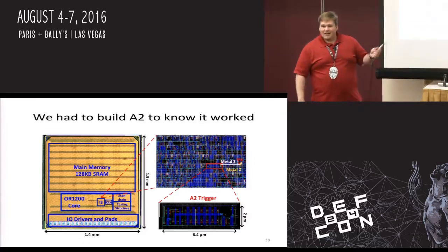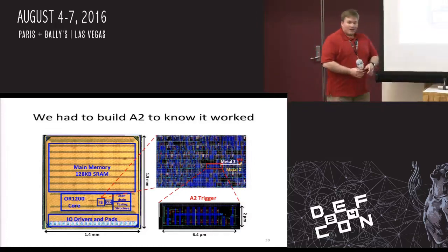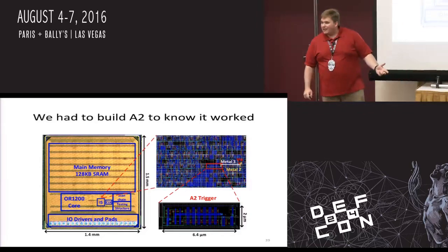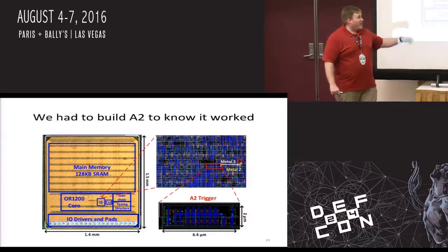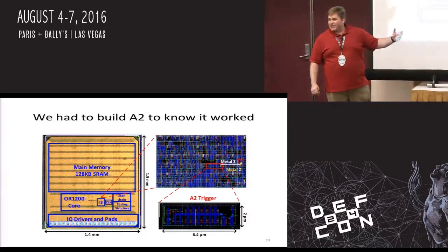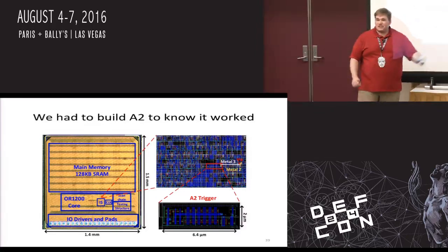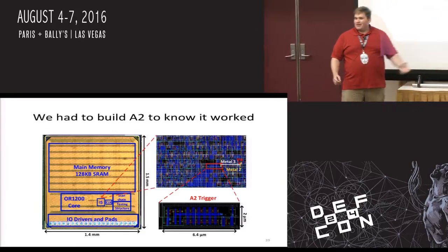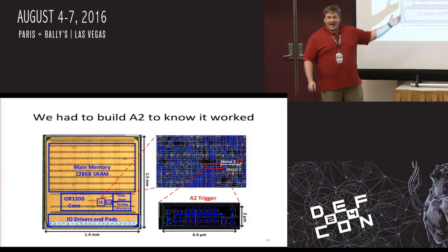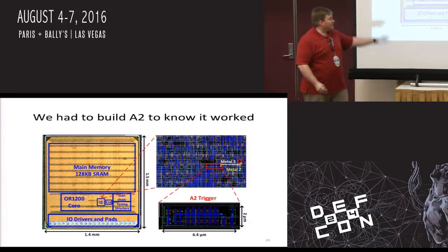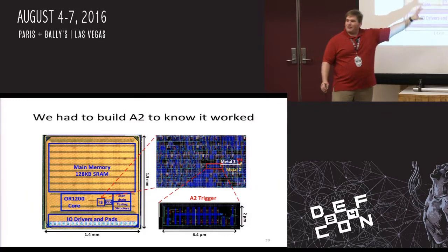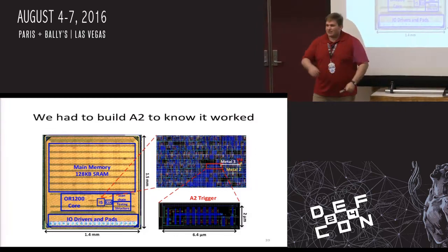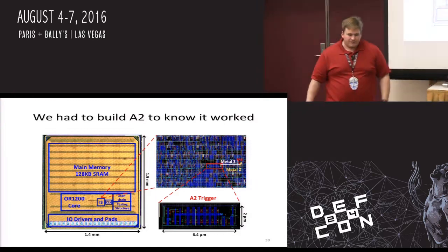We actually built this. Because it exists in both the analog and digital domain, it's not something we can run in an FPGA. We ran hardware simulations, but the hardware simulations can't do the analog behavior. We ran analog SPICE simulations, but again, you can't simulate a whole processor, so that simulated the analog behavior of our trigger. To put them together, there's no tool that exists for that, so we had to actually build a chip. And so this is the OR1200 we built. You can see a couple of levels of zooming in to see basically our one cell attack in amongst many other cells, about 100,000 transistors worth.